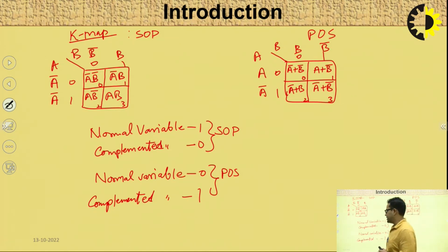Now the next thing is how we are going to discriminate between the 2 variable K map and 3 variable K map, because till now the coding that we are using inside the cells is in binary form, but we know that the K map uses a representation called gray code representation. So whatever the cell values, they will be represented in gray code.